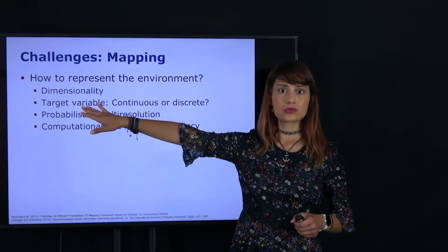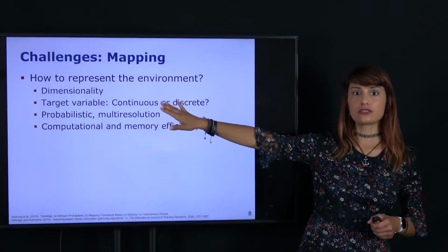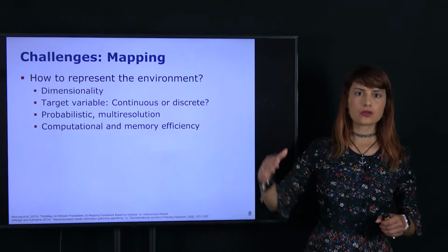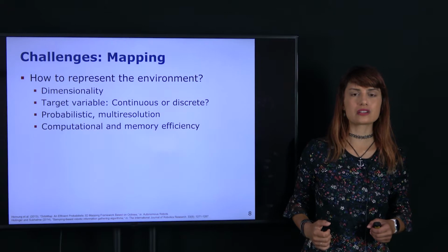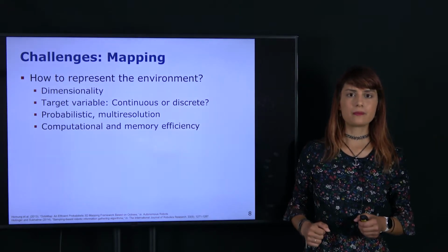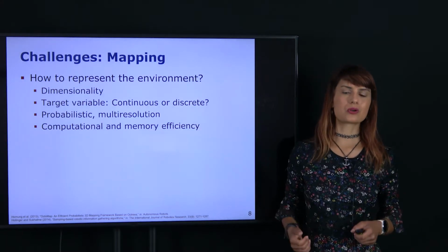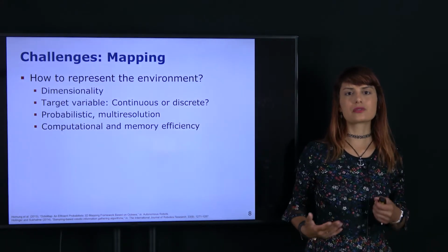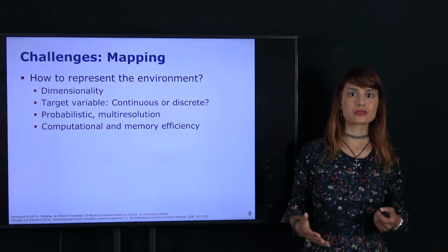Some problems are 2D. For example, the case of a UAV monitoring an agricultural field or any terrain. If we only have a top-down view, a 2D or a 2.5D representation would be sufficient. But in the case of a robot monitoring a room or even a city, we might need large 3D maps to capture all the structural information associated with that environment.